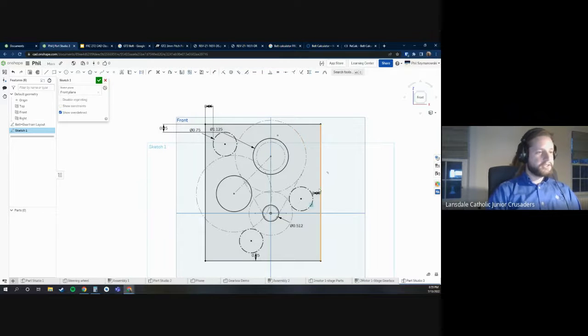Again, I suggest that you make these not individual dimensions and that you draw a line so that you can change them all at the same time. You draw a line from here to there, and a line from here to there, and a line from here to there, and you make them all equal. That's a better way to do what I'm trying to show you right now. I'm just trying to get through this quick because I have 5 minutes left.